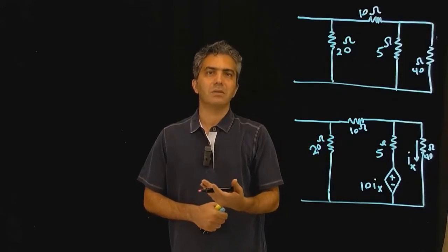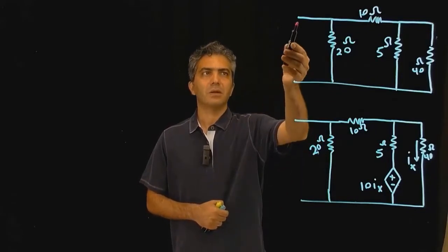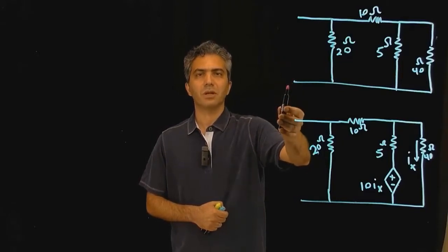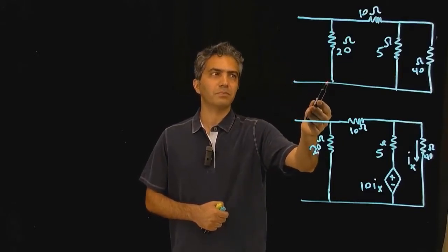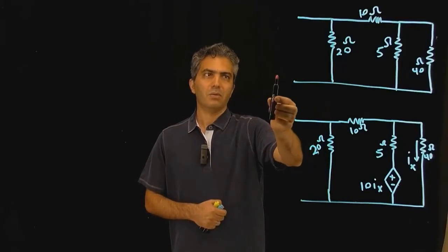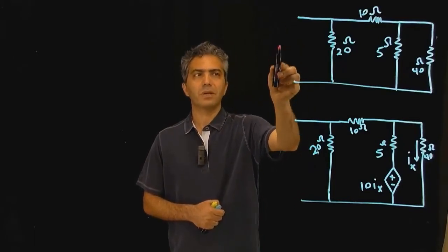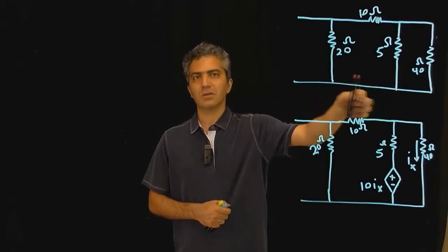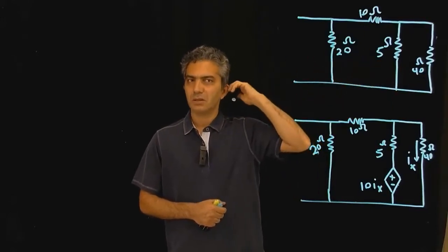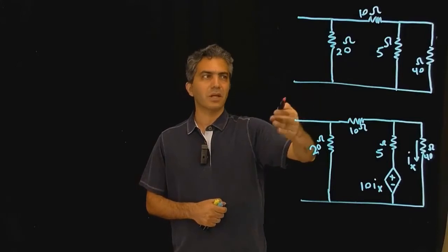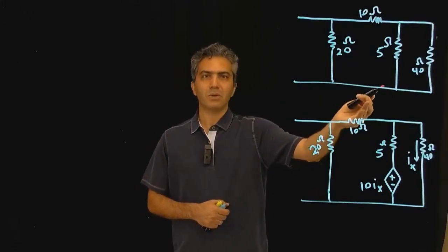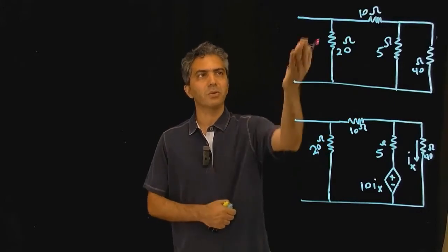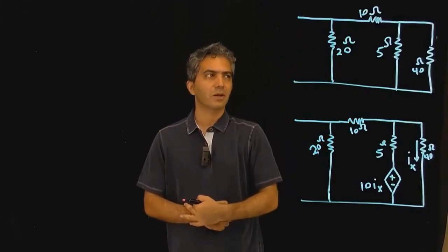And what that means is that the open circuit voltage here would end up being 0. The same way with a short circuit current. So if I leave this as a short circuit, same thing. Since there is no source of energy here, there's no reason for any current to move about, and therefore all the currents end up being 0, including this current for the short circuit current.